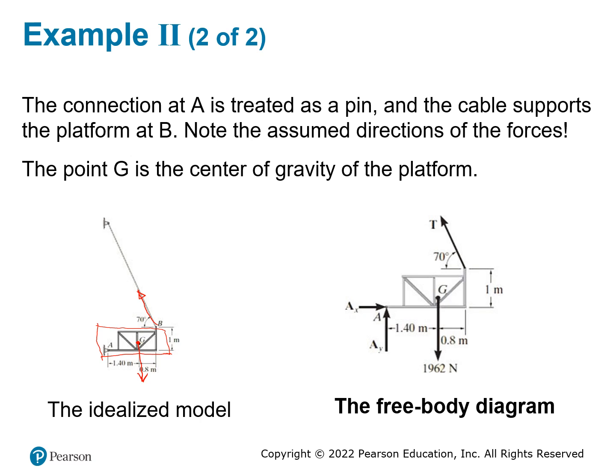And are there any other forces? Well, here you have a pin. If you have a pin, we're going to have Ax and Ay. So our free body diagram is going to have Ax and Ay at the pin right here. The center of the mass is going to give you the weight, which is not the mass. And you have a tension force that goes along the cable. So this is the tension force. This is the free body diagram.